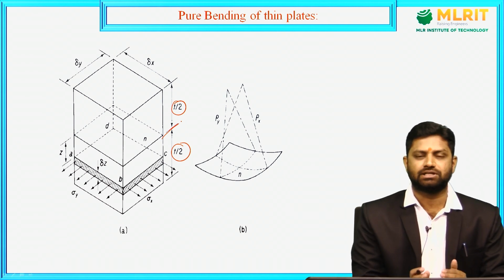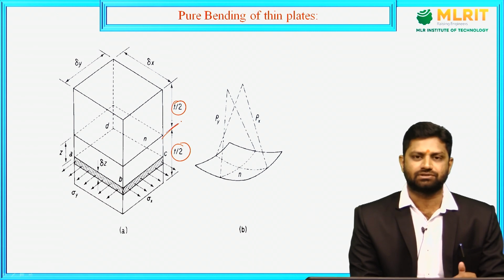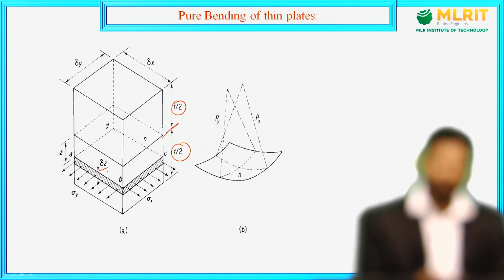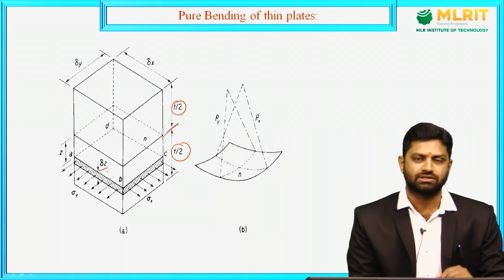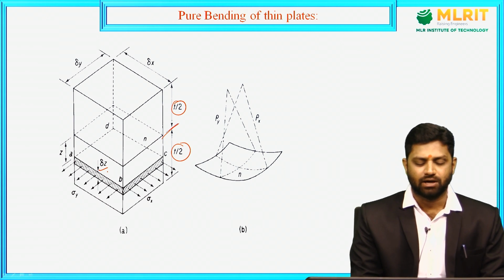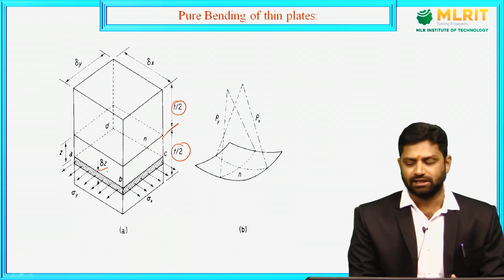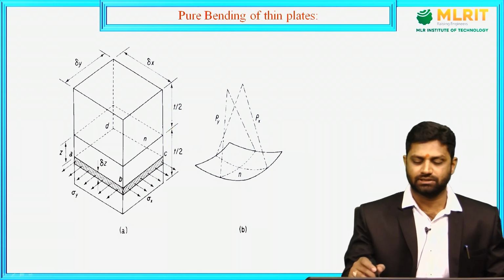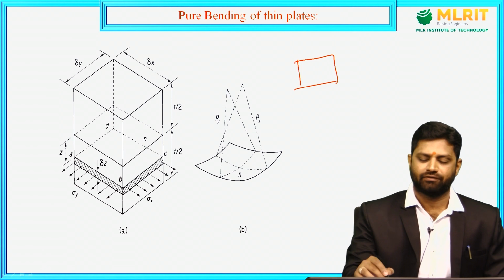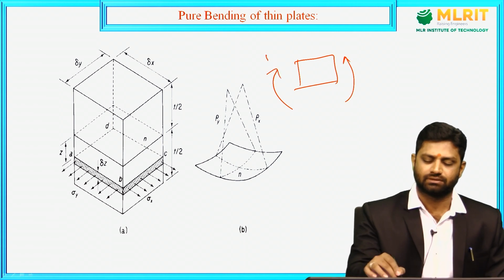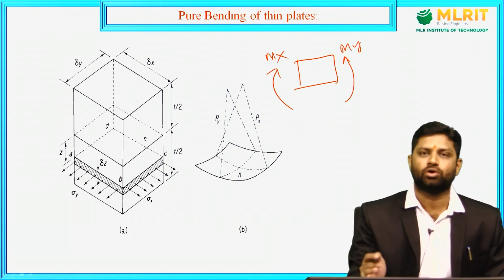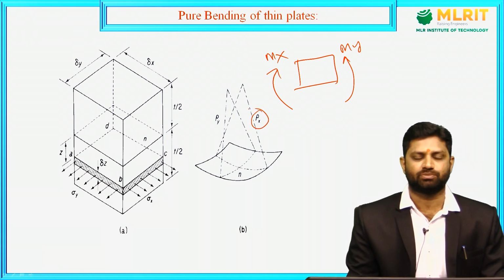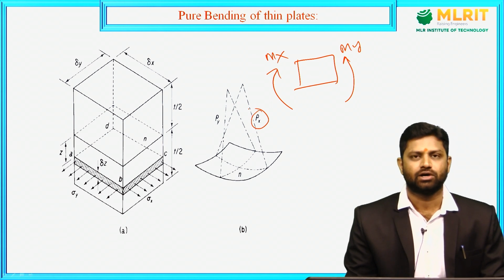So we considered one element in which we represent the stresses sigma x and sigma z, and we have also assumed that the elemental width is delta z. Now let's visualize a normal thin plate. When you apply the bending moment mx like this, it is going to take a curvature, right? That curvature is shown with respect to some reference point and is designated as rho x.